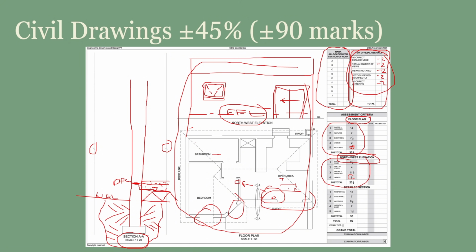DPC, the damp-proof course. There's always a DPC in line with the concrete surface bed at the top. The walls have the same hatching that you've applied on the floor plan. Double line spacing, all the way up until the roof. You will most definitely need to draw in a window or a door. When it comes to a window, you will have a lintel at the top, either a double or a single, most likely a double. It's going to go through an exterior wall.